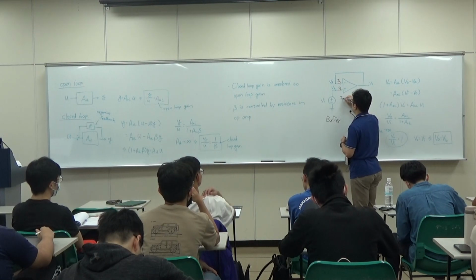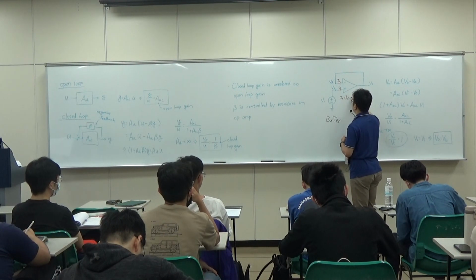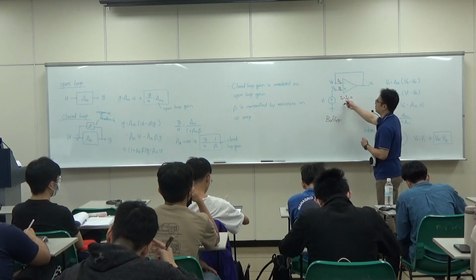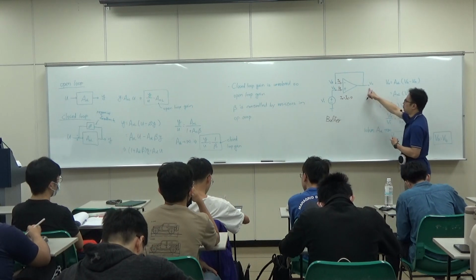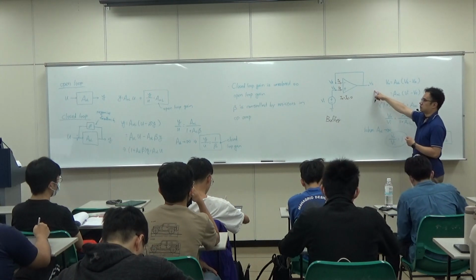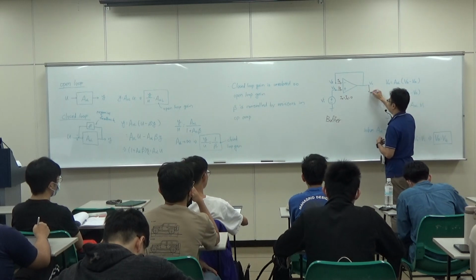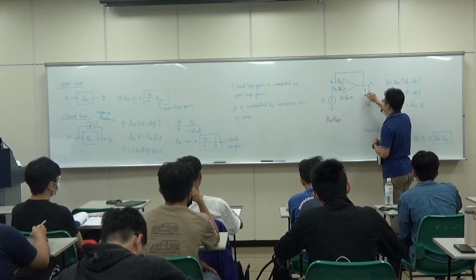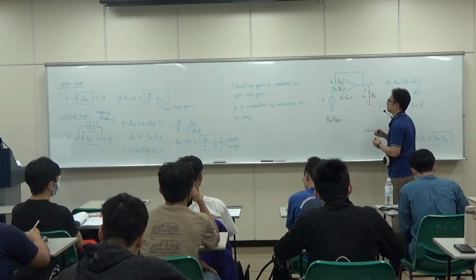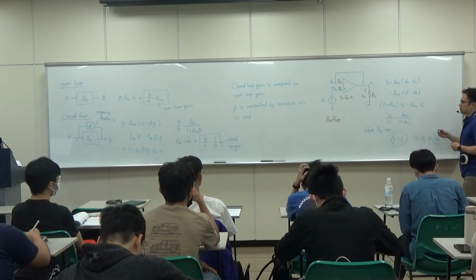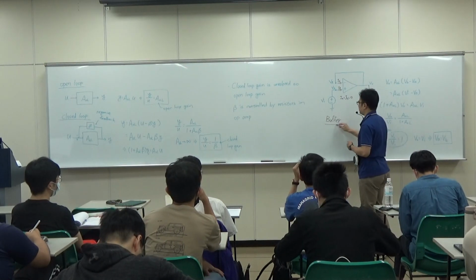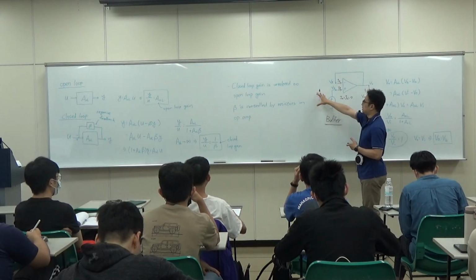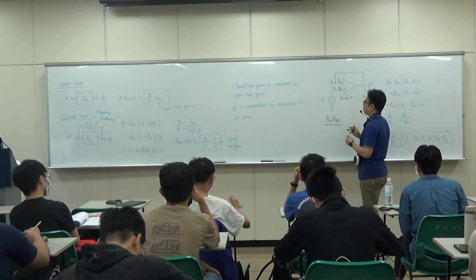So IA equals IB equals 0. In real case, it will be very small. And output will always be VO. So no matter what kind of load it connects, the output voltage will always be VO. So it is a buffer, and it can prevent the previous circuit from affecting the output.